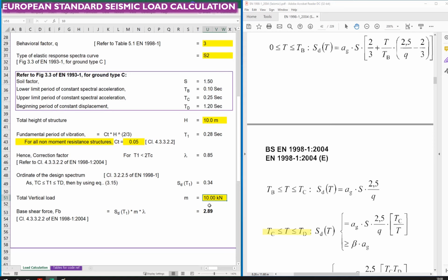The seismic mass is to be considered as the self weight or total weight of the structure, incorporated with all the imposed loads. In addition to that, in some technical specifications, the project owner may require including part of the live load, say 20%, 50% or 60% of live load, along with the structural self weight and structural and non-structural elements of any building.